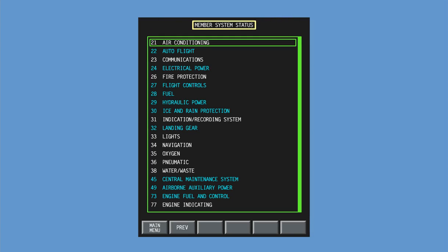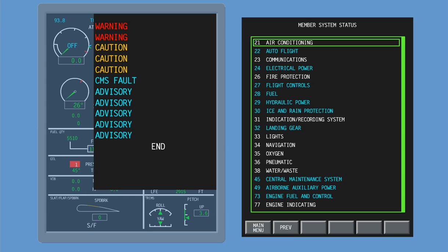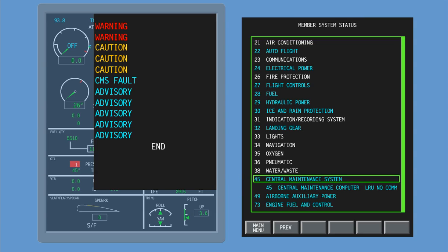Troubleshooting is started with the status page. This is because when the aircraft is on ground, many of the systems are switched off and they will be generating CAS and maintenance messages, but in fact, at this stage, they do not represent failures. On the status page, you can identify which systems are operational and which are not. By looking at the non-operational pages, which are identified by cyan color, and cross-checking them with the active maintenance messages, it is possible to differentiate the messages caused by real failures from those caused by the current aircraft status on ground.